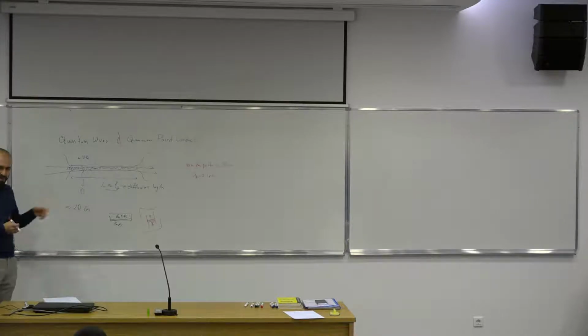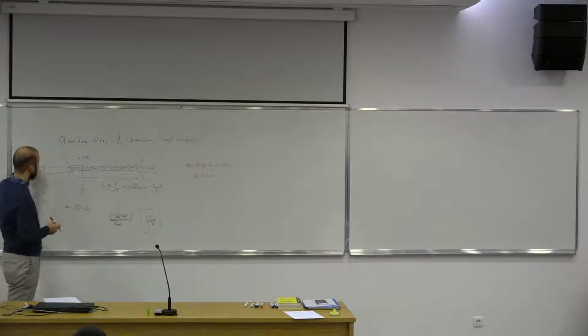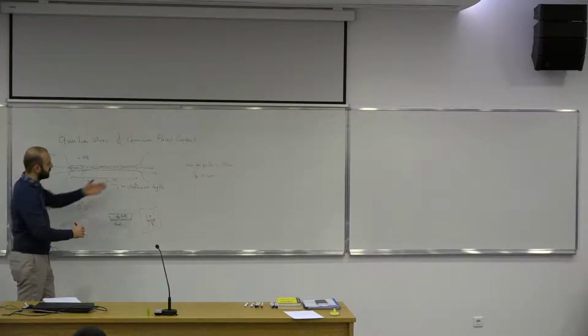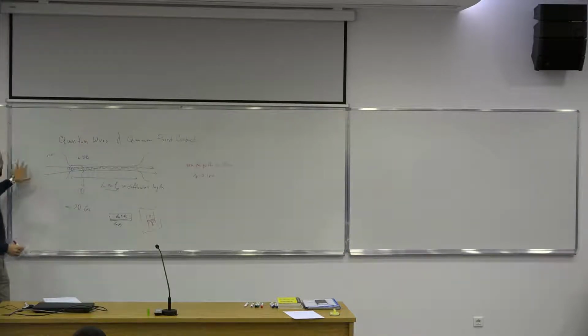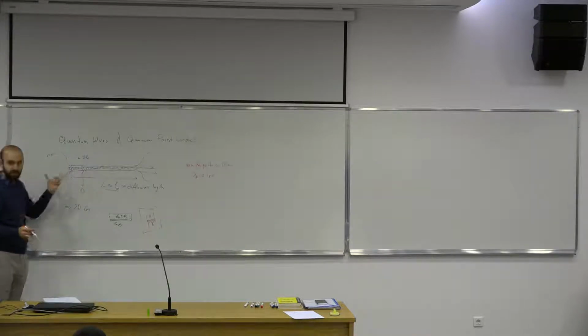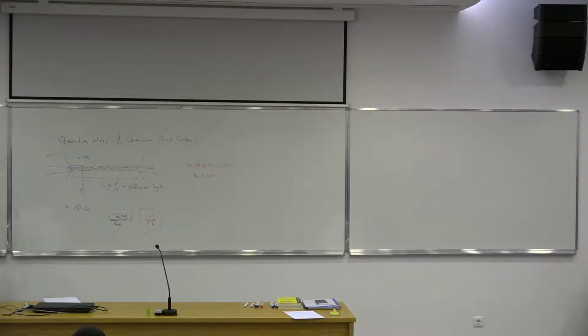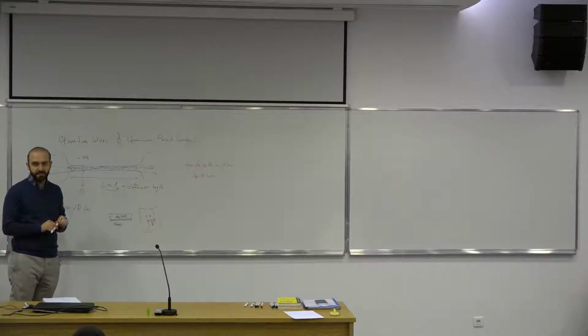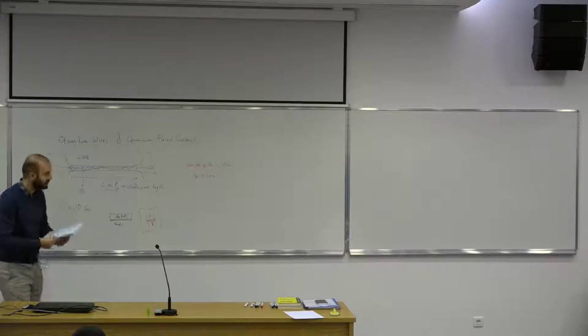So because of that reason, as we'll see in a moment, we assume that we have a reservoir here that contains lots of electrons, which is our metallic contact, if you like, and here as well. And as we'll see in a moment, this assumption says, okay, I have plenty of electrons here with lots of different energies, and one electron can enter into this nanowire without any obstacles, or real obstacles, I should say. But in the case of carbon nanotubes, it has to tunnel through a barrier to be able to get into the carbon nanotube first. So in that case, we don't see most of the quantum wire effects. So really, most of the experiments, or most of the stuff that I'm going to explain, has been performed on confined 2D electron gases. Okay, and this was a very broad answer to your question, I guess.